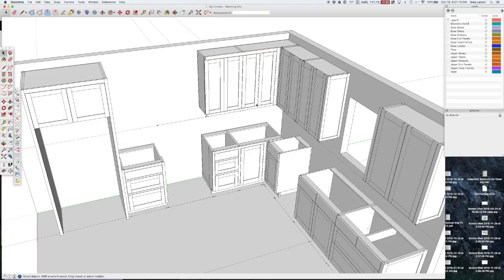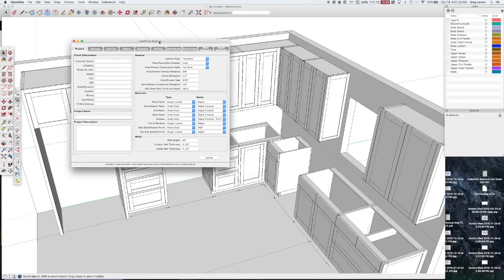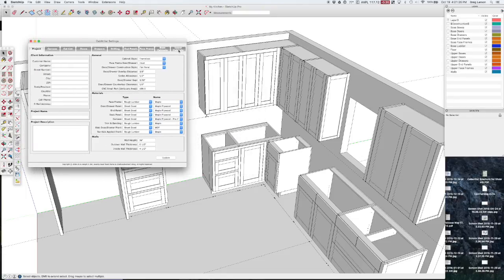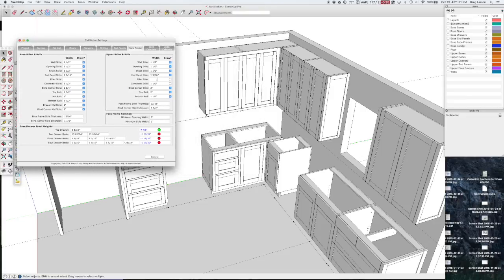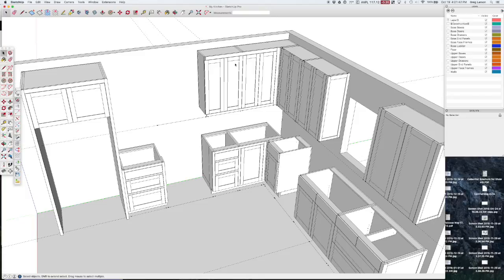And it redrew the cabinet, missing the connector style, but it's also missing this style over here. And that's because I used something called a filler style that is new in this version. And if you'll notice, nothing was filled in for the filler style for width. So I'm going to call that 1.5 inches. I'm going to turn that back on and see what we get.